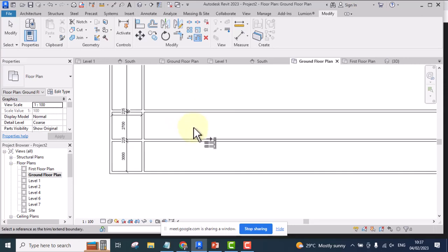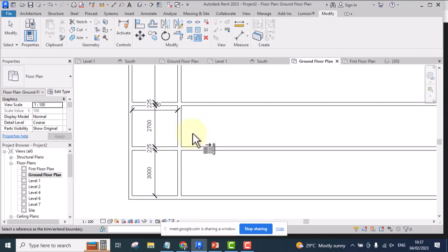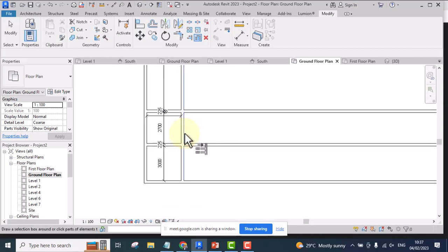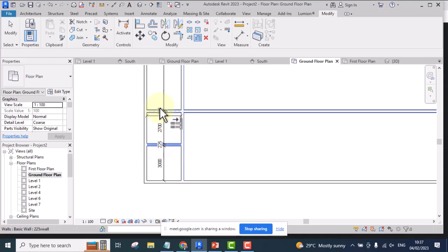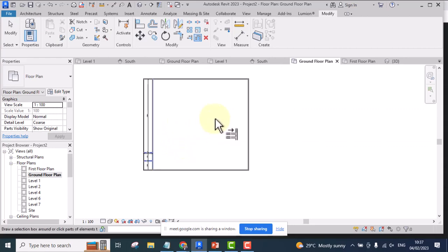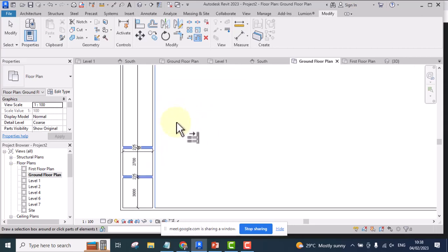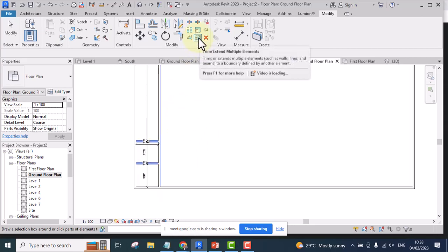For me to do that, as I picked it now, I click on where I want it to go. So I click on this place. That is where I want to cut it to. And go to the back of it. Don't click the front. You go to the back, click, and click. You can see it has cut them off. Now the command is still on, meaning I can still go ahead and continue the trimming. Now these two work for both trim and extend.